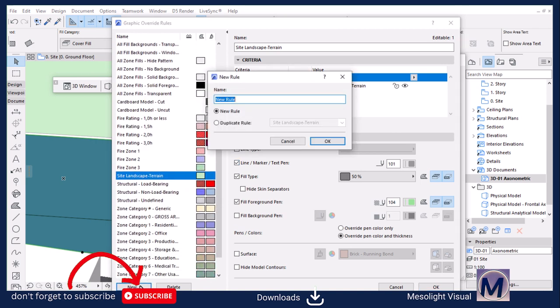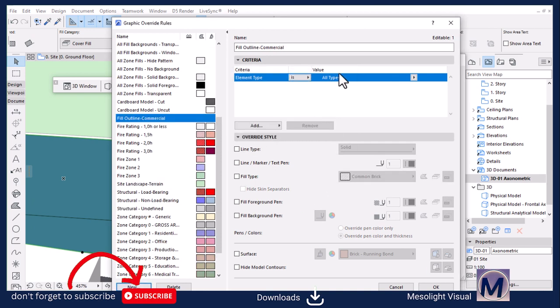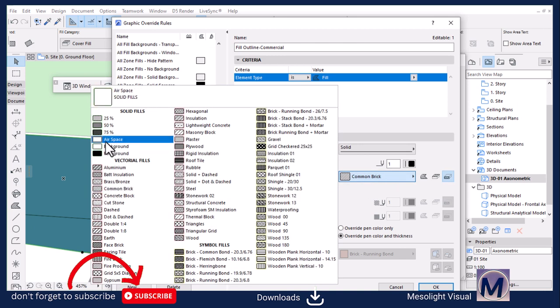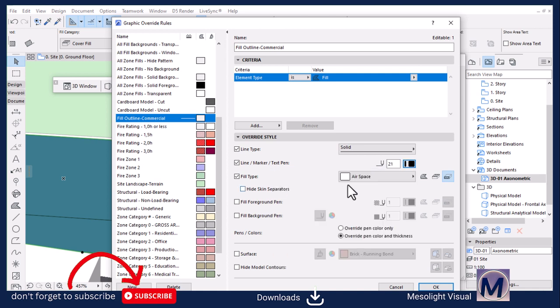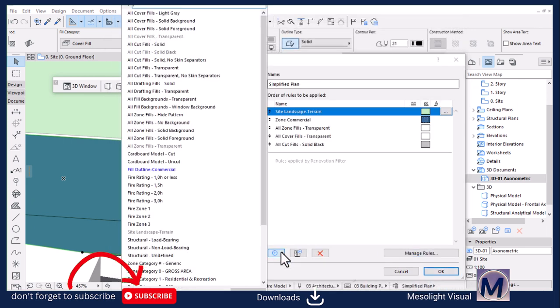Let's create a new one, and then we say fill outline. Let's say commercial. Hit enter. Element type is going to be fill. Then we're going to override the line type, the line pen, and the fill. The fill is going to be airspace. This is going to be on 0.35. Make sure cover fill types is selected. And hit OK. Let's edit.